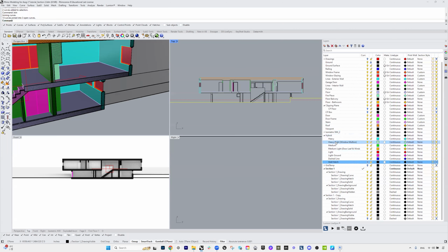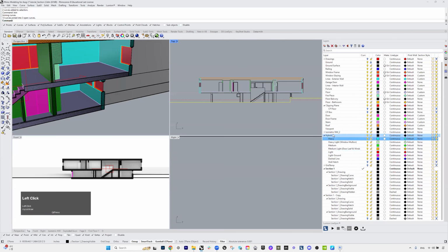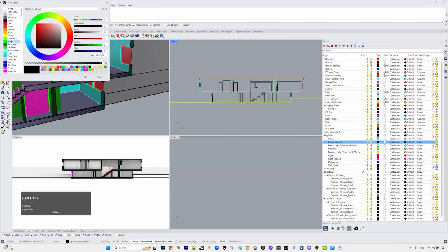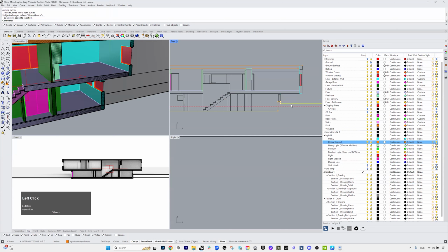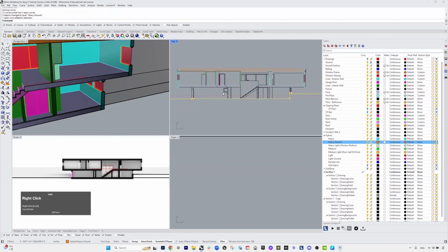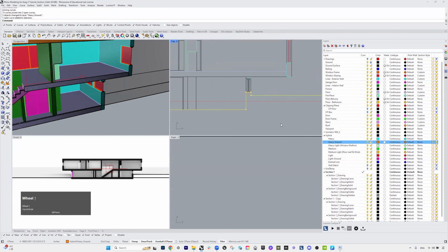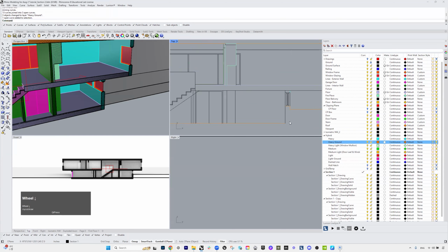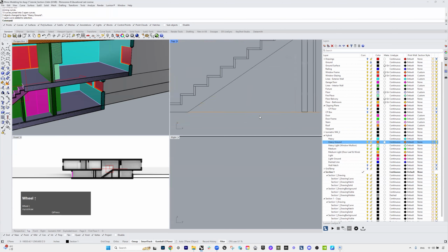I'm going to create a new layer called heavy ground, change object layers for that, and say orange maybe. Then you would have this continuous line to define the ground structures. Let's just say ground lines, even though part of the building structure is becoming ground lines. I think that's okay.